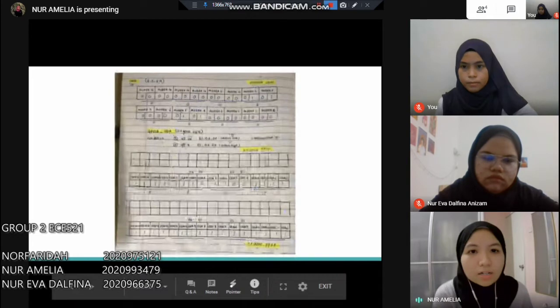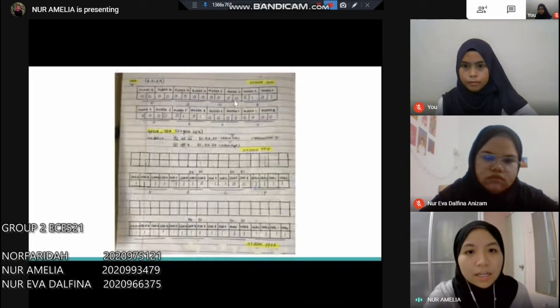Then we proceed to the ORR. We need to put 01 in pins 4, 5, 8 and 9, which gives the value 0x000F0500. Next, GPIOB ODR, where we have two conditions.